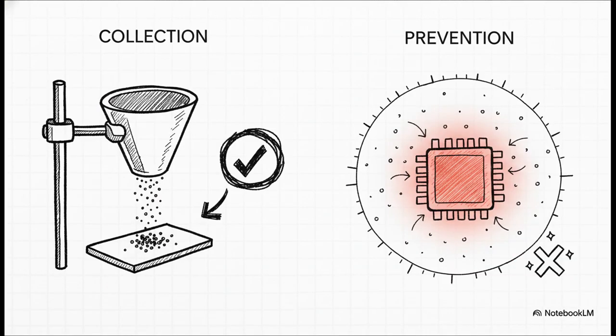So, what are the key things to remember here? First, its efficiency is nearly 100% for particles all the way down into the nanometer range. That makes it a gold standard for sampling. Second, it's perfect for collecting samples you want to look at under a microscope. And third, and this is a great point to make, the same idea is used in reverse. In semiconductor manufacturing, they keep sensitive surfaces just a little bit warm to create a thermophoretic force field that literally repels any contaminating dust particles. How cool is that?